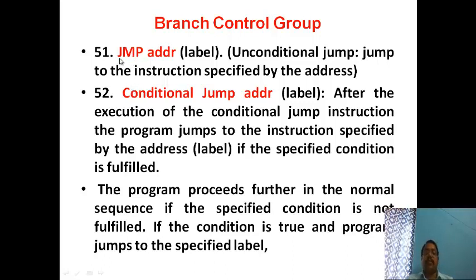There are two types of jumping or branching instruction. When you do it by jump, you will write JMP followed by the address. With call, the program counter, once it sees this instruction, the next value of the program counter will be moved to the stack, whereas in case of jump it will not be moved. So it will just load this address to the program counter and proceed.